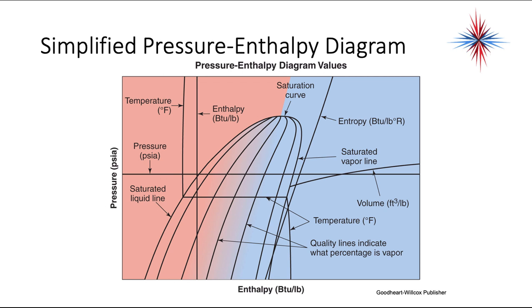So again, this is a temperature enthalpy diagram. It shows us temperatures, it shows us enthalpy, which is heat content, and it shows us the saturation curve for each part of the blend.